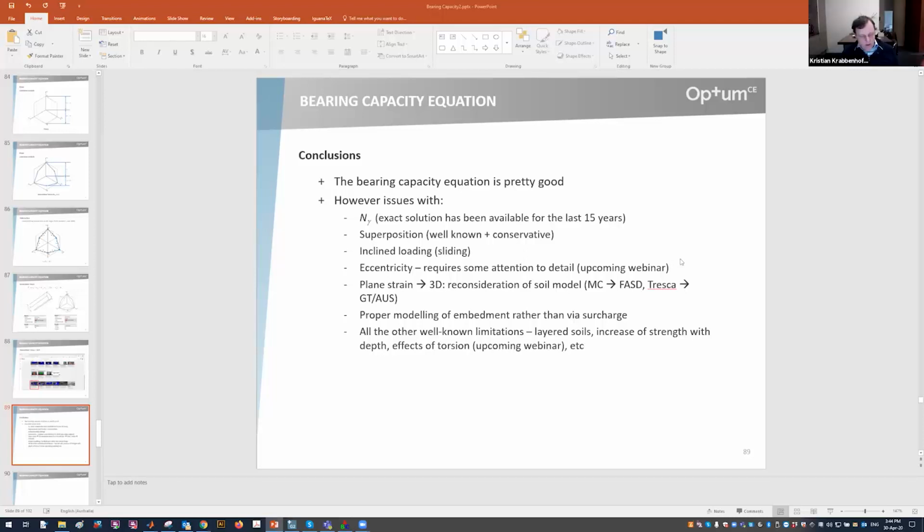That's a good question, because in a way it's neither of those two. We have a slightly different approach to solving the equations, and it is via optimization. All of the results I showed you here have been calculated using limit analysis. Limit analysis is an analysis type that naturally generates an optimization problem: determine the highest possible lower bound, the smallest possible upper bound. And it's a calculation that can be done in one quick go.